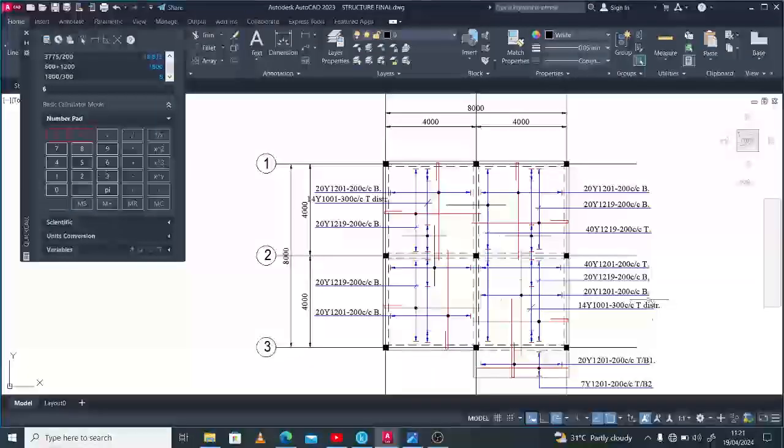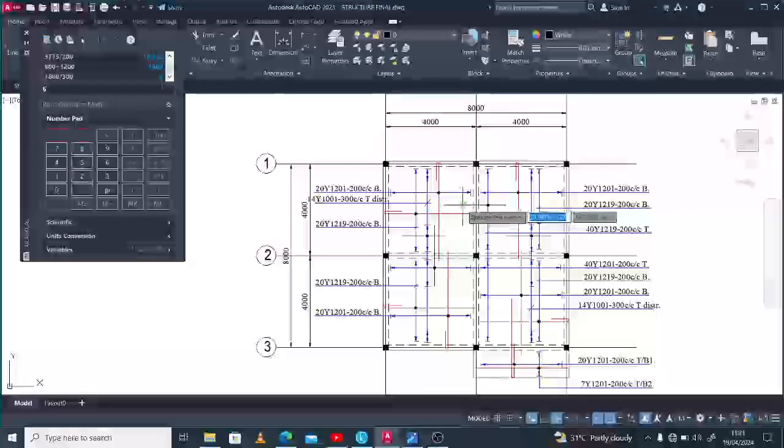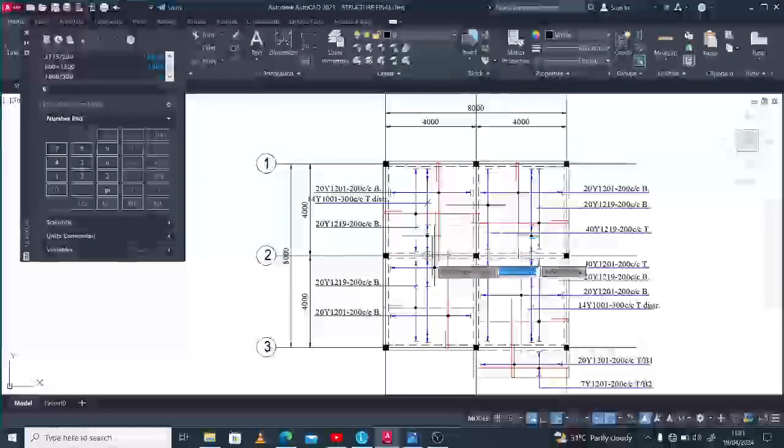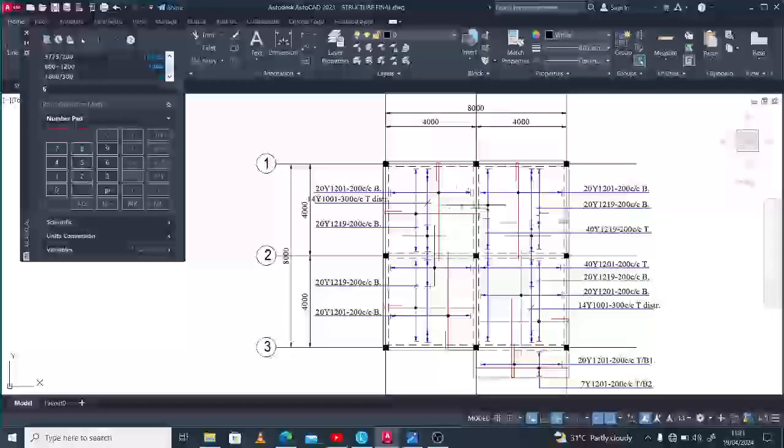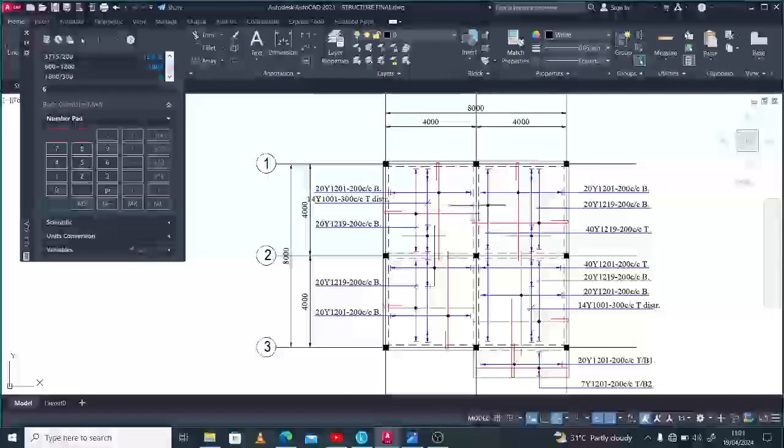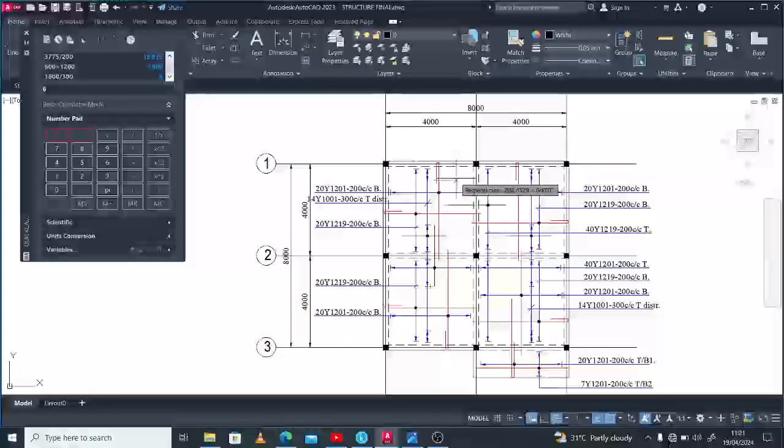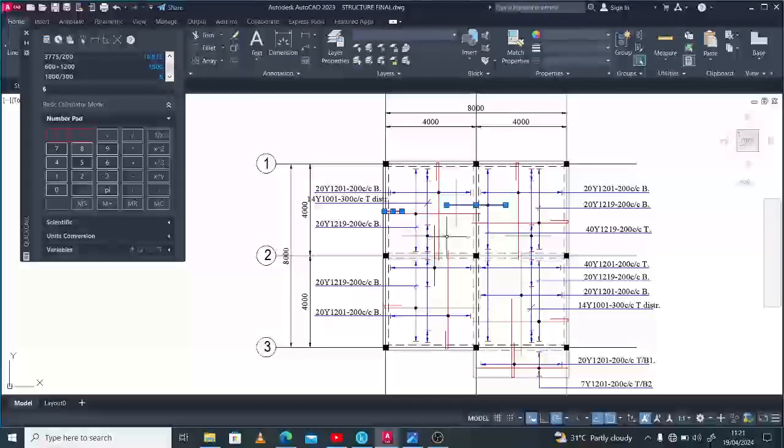If you're working on varying spans, you have to create what works for that particular panel. All right. So on the other direction, we need to distribute this reinforcement. We have clearly distributed this top reinforcement. So we need to provide a top distribution, which is going to be between this, just like I did previously, and this. Then we have the bar. What I did on this horizontal is between this top and this top. Then we provided this to span all through on the top reinforcement. Then on the other end, it will be between this and this. Very, very clear.